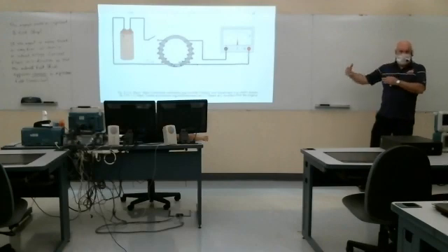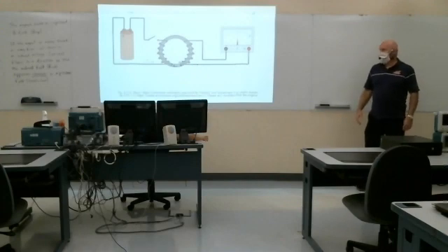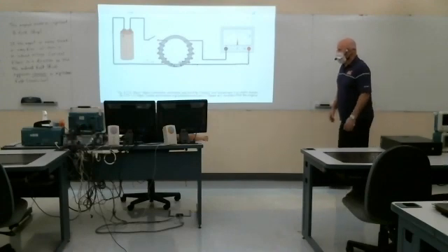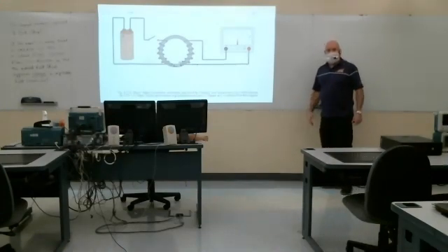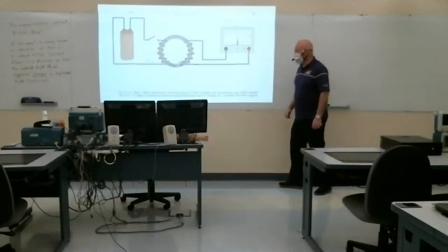So they have another transformer near the house where they step it down to a much safer 120 volt level. And then the currents consequently are much larger coming in the house, but that's over a shorter distance. So that's kind of why we use AC power, because transformers exist and transformers only work for AC voltages.